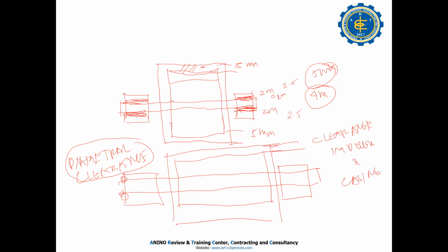Here, you must know, because if the time comes, the bearing may not be damaged, but the babbitt becomes thin. You know the maximum clearance at which you must shut down before the impeller of your gas turbine hits the casing.